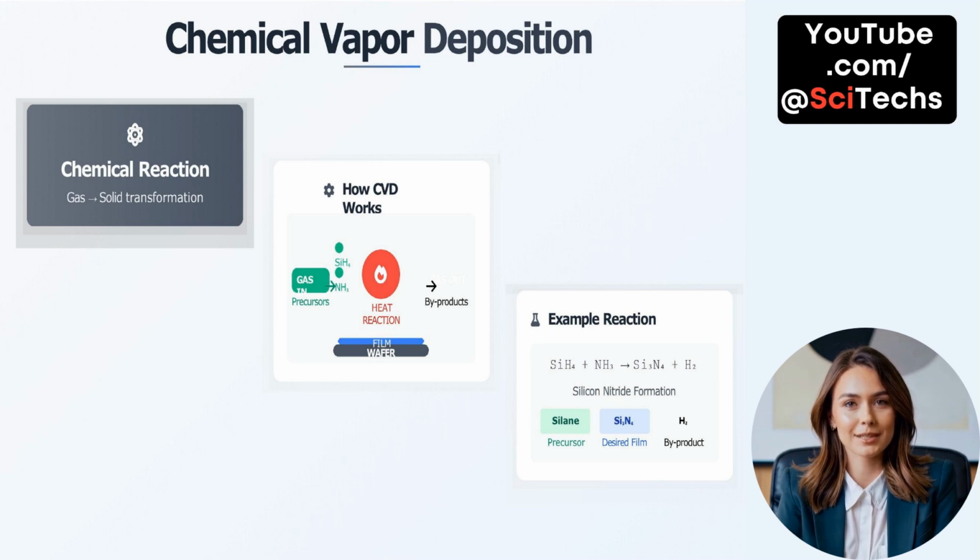The reaction is SiH4 plus NH3 yields Si3N4 plus H2. In this case, silane and ammonia serve as precursors. Silicon nitride is the desired solid film, and hydrogen gas is released as a byproduct. This entire process allows for precise film deposition on complex surfaces, making CVD a versatile and essential technique in semiconductor manufacturing.